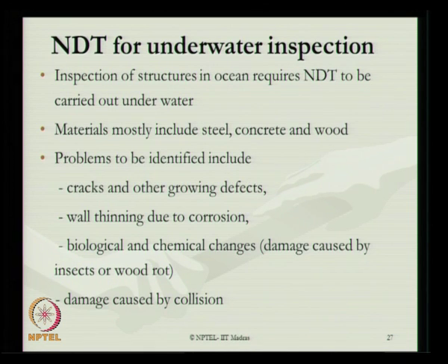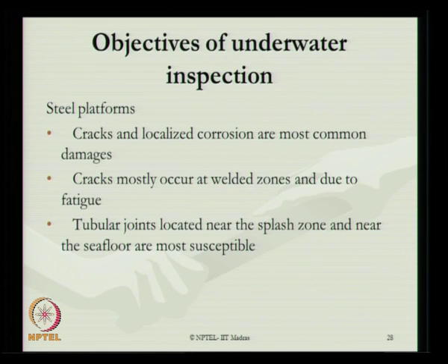Problems to be identified include cracks and other growing defects formed in the material, wall thinning which can occur due to corrosion, and biological and chemical changes which can cause damage, affecting wood or any rotten area of the wood. Damage caused by collision of ships and tugboats can also be identified, which generally happens underwater, and NDT should be used for this kind of inspection.